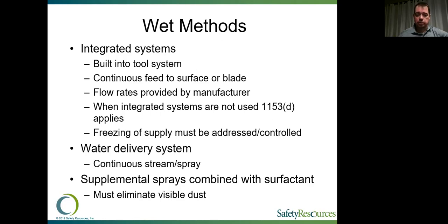That is exactly what is meant by it, which is, there has to be a continuous stream of water applied at that point that would also be able to reduce or restrict the amount of visible dust that's coming off of it. In general, with all of these methods, one standard that can be applied is, we don't want to see visible dust, but we also don't want to see it accumulating.